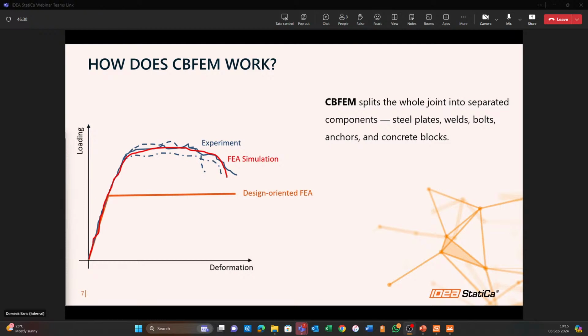Strength analysis is the most important analysis of the joints, and the check of plates together with the checks of components are performed by elastic-plastic analysis. The analysis of joints is materially nonlinear, and the load increments are applied gradually, and the state of stress is searched for.